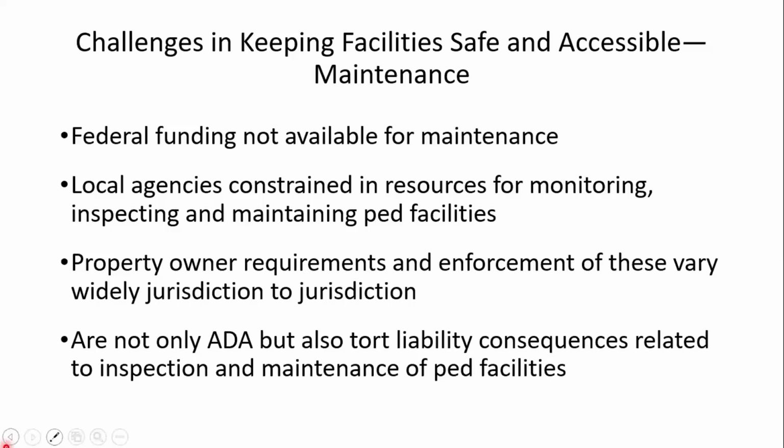And also, not only are there ADA consequences, meaning civil rights lawsuits if a sidewalk section is not accessible to those with disabilities, but if, for example, we have a heaved up sidewalk slab and an able-bodied pedestrian trips and falls at that location, there may be tort liability consequences where someone may file a personal injury lawsuit to seek compensation for their injuries or the harm that they sustained.